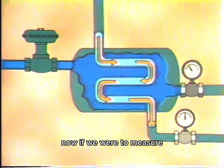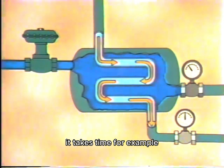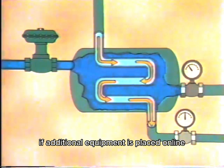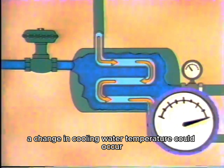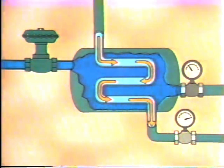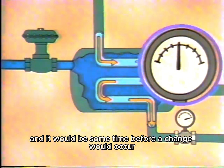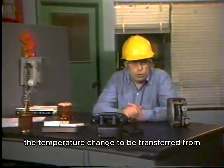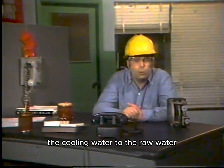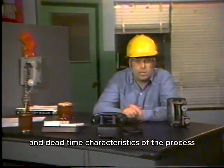Now, if we were to measure the time it takes to transfer the heat, we'd find that the transfer doesn't occur instantly. It takes time. For example, if additional equipment is placed online, a change in cooling water temperature could occur. And it would be some time before a change would occur in the temperature of the raw water. The time it takes for the temperature change to be transferred from the cooling water to the raw water is a delay in the process. It's caused mostly by the resistance, capacitance, and dead time characteristics of the process.